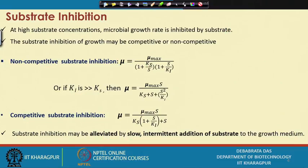We can have two types of feeding in the reactor, either constant intermittent feeding or constant volume feeding. Like this, your organism can use more substrate during the fermentation process. This is how we can partially overcome the substrate inhibition problem.